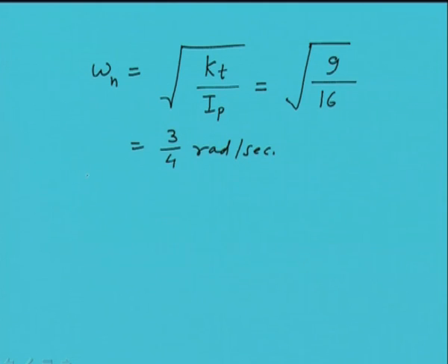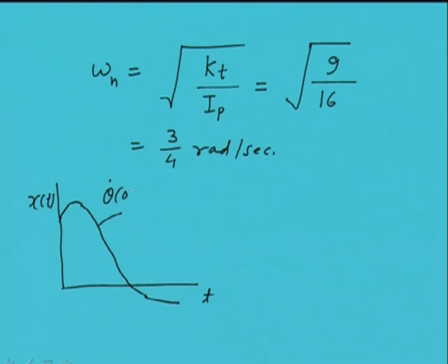And the condition which we derived earlier, that maximum velocity we should have to hit the door, or if we recall the previous lectures, in which we had the initial velocity such that it crosses the static equilibrium once, that condition is that the angular velocity at time t equal to 0, if it is more than minus of the initial displacement, then it may cross once. So if we have less than this, it may not cross once. So we are keeping that equal to, so that we just get the limiting case.